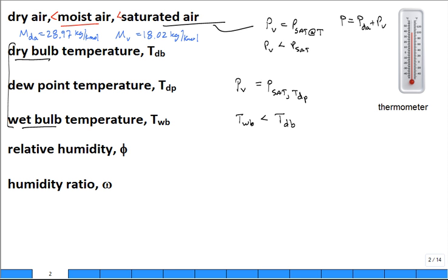So you can have water on the inside of windows in the winter inside your house. That's condensate from the low temperature of the window pane being below the dew point temperature of the air in the room. And then you can have other great applications. Why does dew form on the grass or on your car in the morning when it's not too dry? Not every morning do you have dew on your windshield or other parts, your rooftop or in the grass, but a lot of mornings you do.